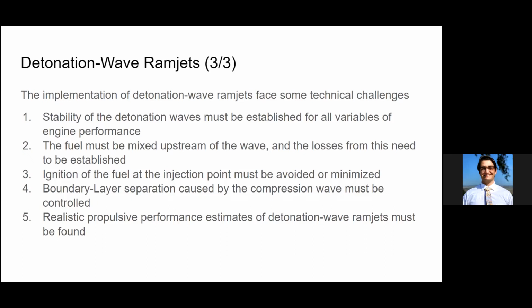The fuel must be mixed upstream of the wave, so you need to establish how much loss you're going to get from mixing that fuel upstream. The ignition of the fuel at the ingestion point has to be minimized or avoided completely, because that would create a combustion prior to the combustion wave itself.